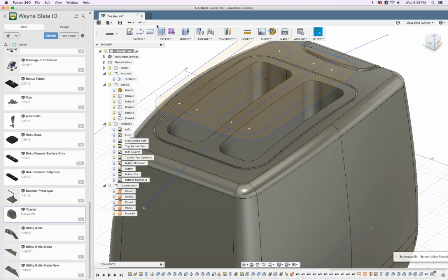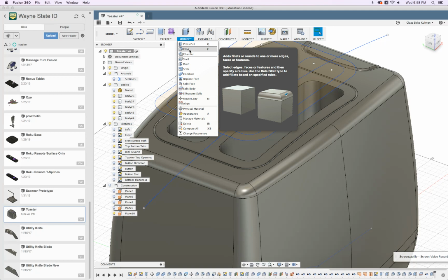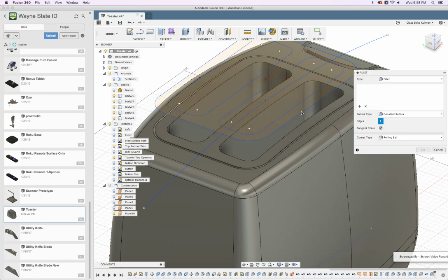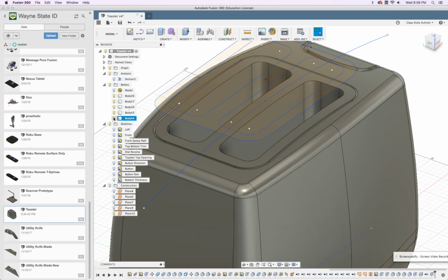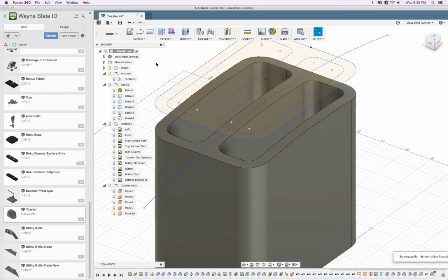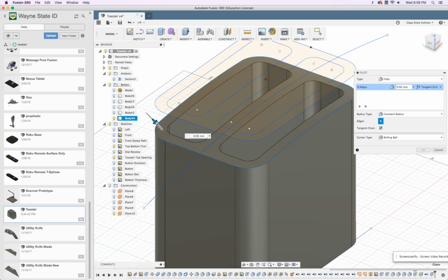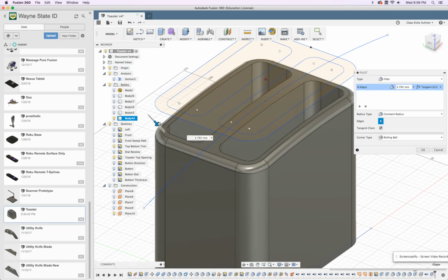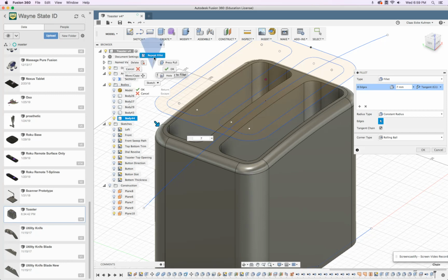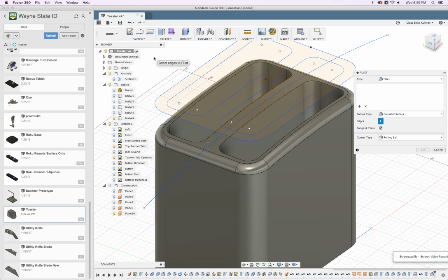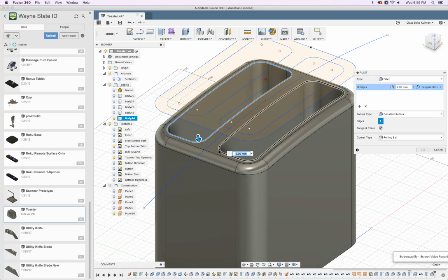Because these parts get very hot. So these metal parts, they should not be close to the plastic. We want to have some good fillets and distances. Which means this one, actually we fillet it pretty big. Let's say 7. And then just touched my toaster. Here we say 2.